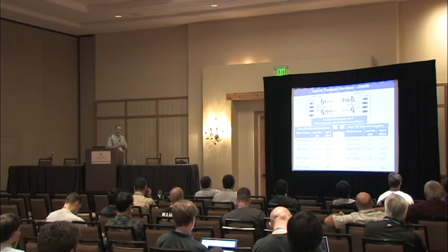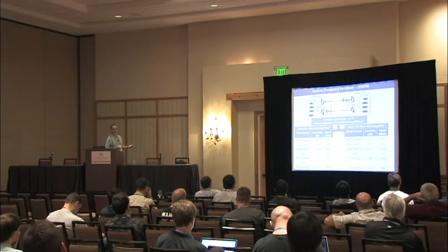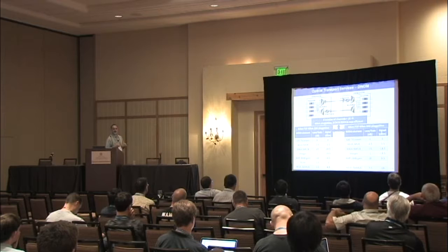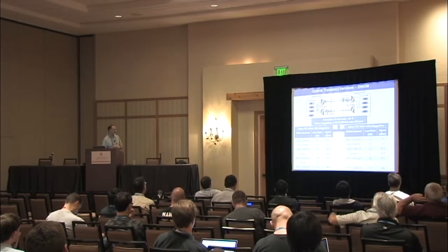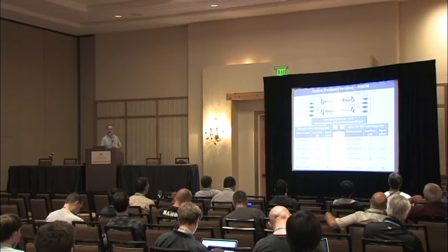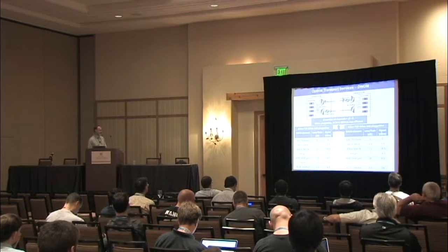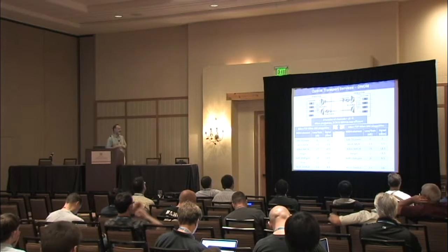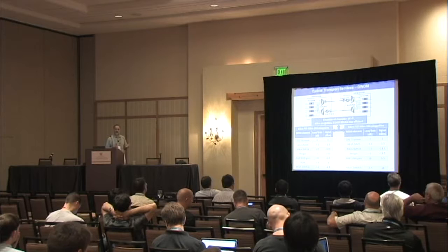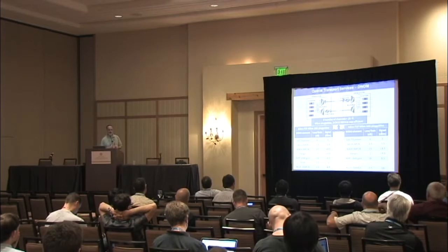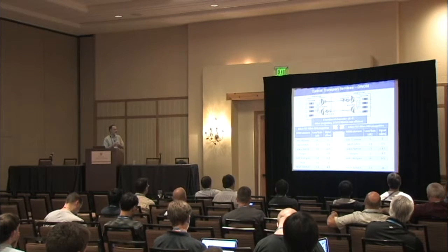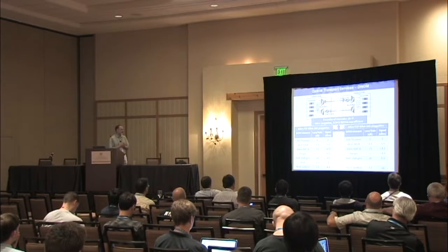Let's do a 60 kilometer, and what's the change here? Being 60 kilometer with 40 kilometer optics, I'm going to have not enough dispersion tolerance. So I need to add not just amplification, but also dispersion compensation. If you go over the chart, it's basically the same. The transmit power is at 0. The 40 channel Mux adds minus 3.5. Then 60 kilometer fiber is minus 15. I'm putting a margin of minus 1 dB, and I'm at minus 19.5, well outside the range of the 40 kilometer transceiver. So I'm putting an amplifier of 20 dB of gain that brings the signal back to plus 0.5.